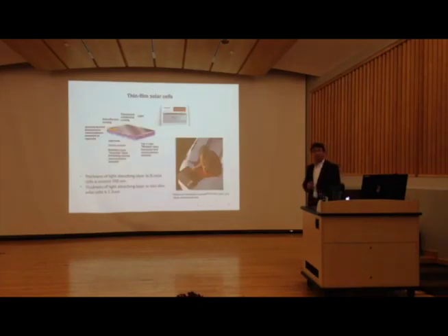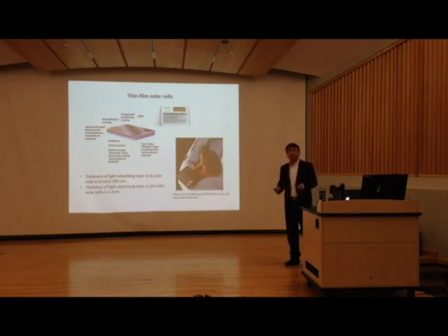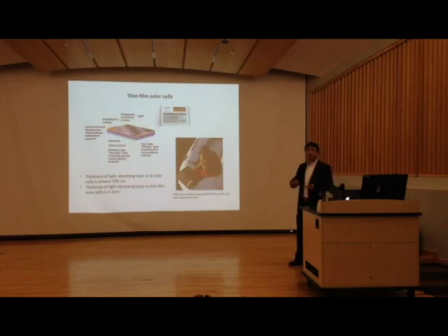For the second generation of solar cells, called thin film solar cells, the way to manufacture them is a bit different. Because now you can use a flexible substrate, or maybe you still stick with a rigid substrate. For the flexible substrate, it's only 1 to 2 micron thickness for the light absorbing material, amorphous silicon, cadmium telluride. So usually people use equipment called physical vapor deposition to deposit this material onto a substrate. And after that, they coat a conductive electrode on top. You should have the device.